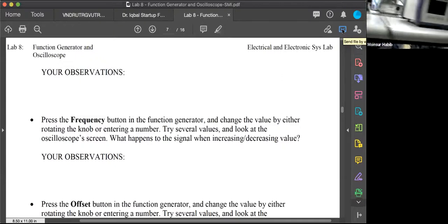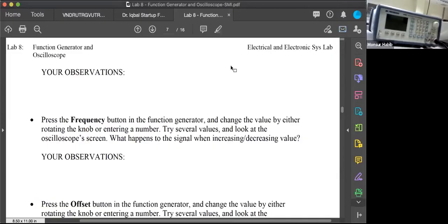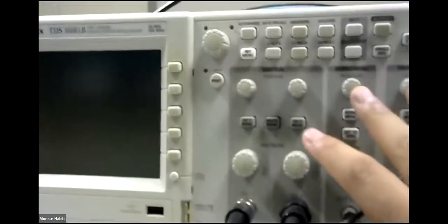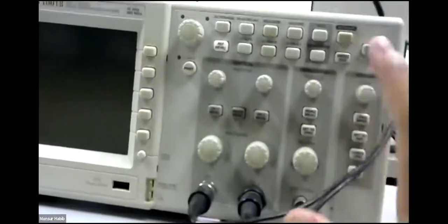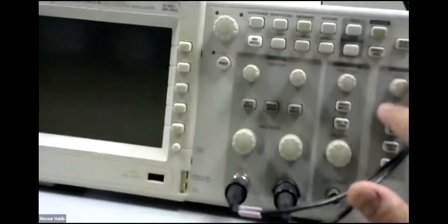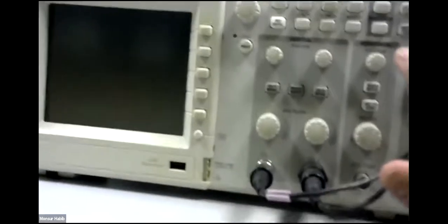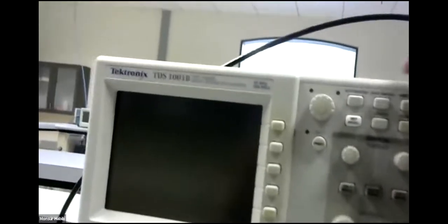So if I were to, let's say, input a signal into it, this one has its own presets, signals, and everything, and it will measure a certain frequency within a certain range. So it might not show up in the oscilloscope immediately. What you need to do sometimes is use this function called auto set or auto range.